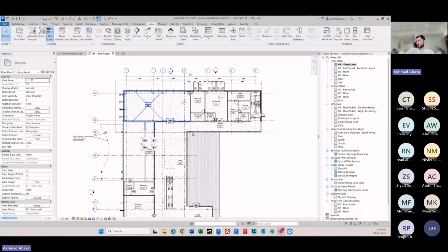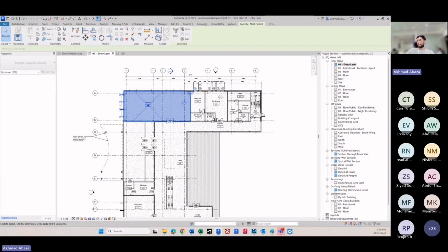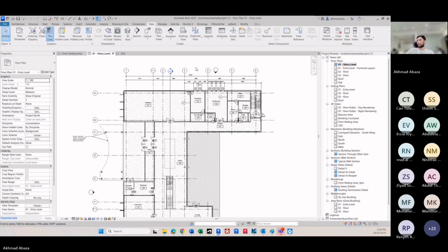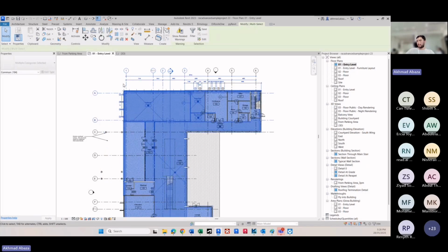So here I just open a solid edged box. We will see that it selected everything within the box. This is selected everything that is outside the box. I want to unselect the grids. So I will hold the Shift key and I will see that the mouse indicator now has a minus. If we press Shift a lot of times, we will get a message. Again, if we press and hold Shift, we see the mouse indicator showing a minus. Now we can deselect by clicking once, or we can deselect using the same.